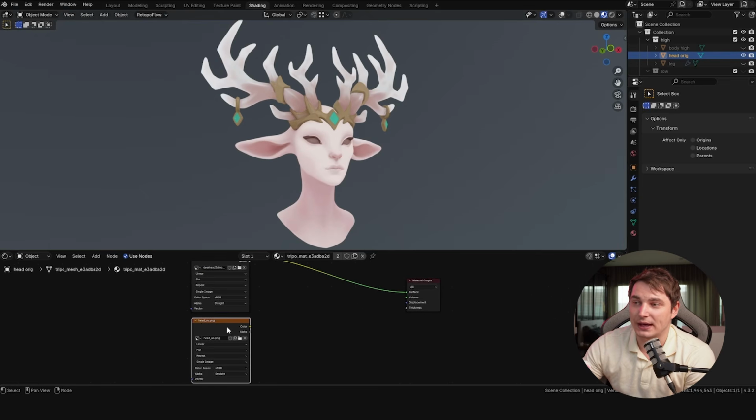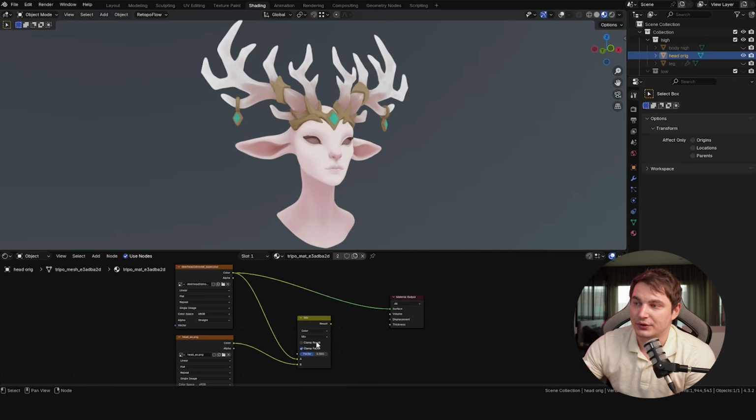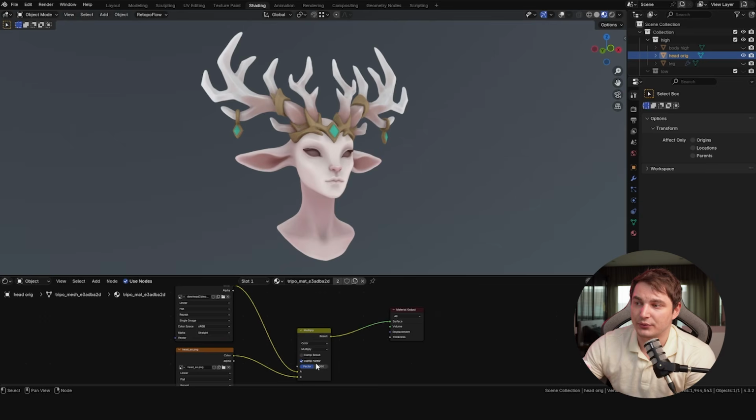We can also drop that to Blender, and here in Blender we're gonna need to add a node called mix color, and we're gonna connect both of these textures and choose multiply. This is how ambient occlusion is usually applied. And here we can control it, like how strong we add shadows. This map is also supported by Unity and Unreal Engine shaders, of course.